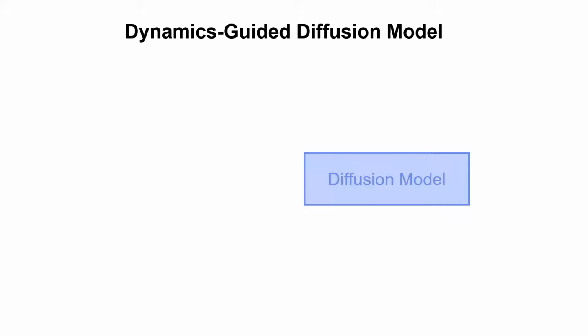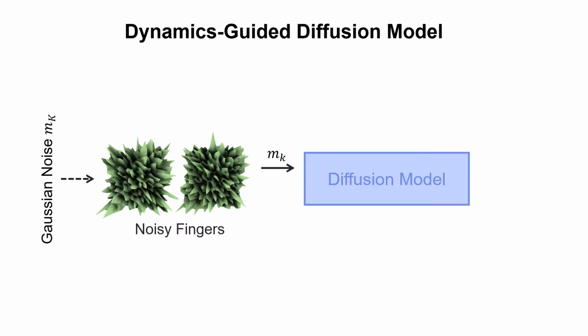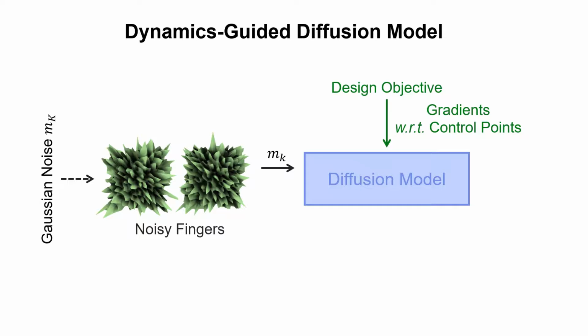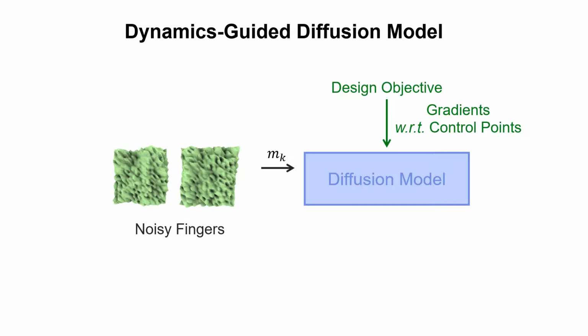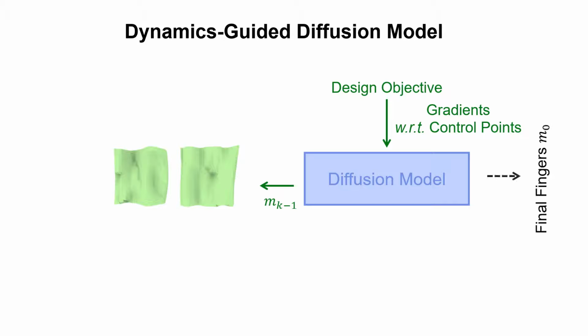With the gradients of design objective, how can we efficiently generate good designs? We first train a manipulator shape diffusion model on the uniform distribution of control points. During the reverse denoising process, we use gradients of the objective for guidance. This process is then iteratively performed, and a task-specific manipulator can be generated within 0.8 seconds.